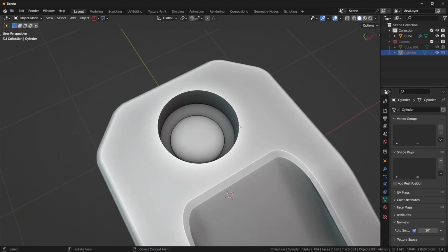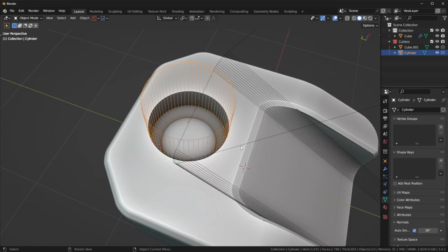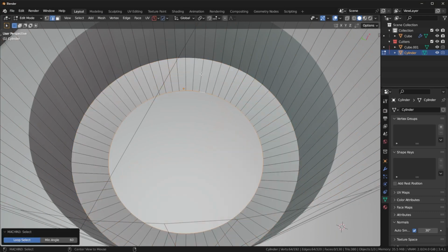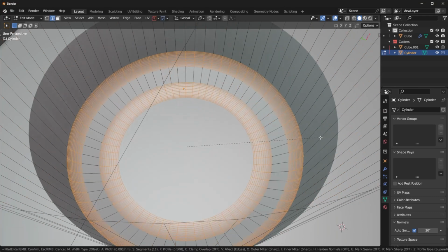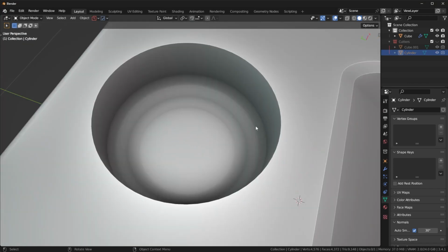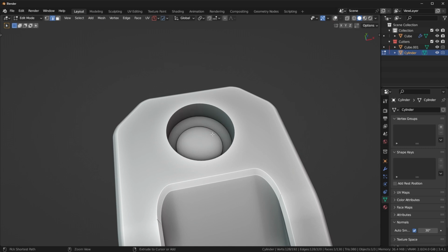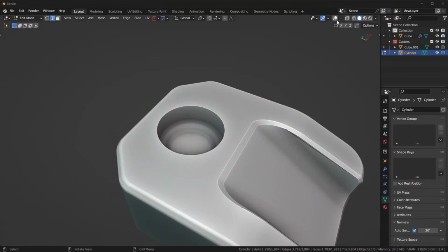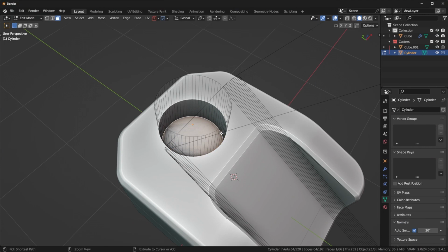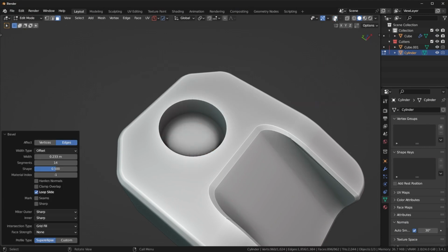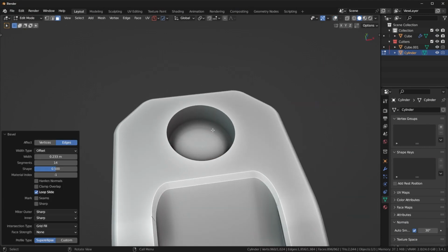And as you can see, it looks pretty weird because this is a concave chamfer. But check this out. I can stack this with some bevels here. Something like that. And you're going to see this looks a heck of a lot better compared to just having a boring chamfer on the inside there. This is why stacking these two together is so important for the visuals of your model. And likewise, if you didn't want to use a chamfer here, you're more than welcome to just use a regular bevel, and you're going to get pretty clean results that way as well.